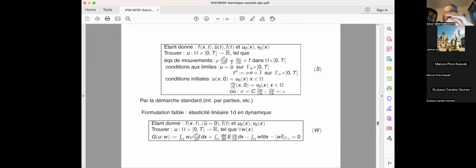And for some simple cases, typically of a bar, you have an exact solution with a wave propagation type of thing. But if the thing gets more complicated, if you go into plasticity, damage and stuff like that, then computing this analytical solution is next to impossible. So we still have to resort to using numerical methods like the finite element method. So just like in non-stationary heat transfer, the dynamics with finite elements will give you only a partial solution to the problem, and we reduce this partial differential equation into a set of ordinary differential equations.